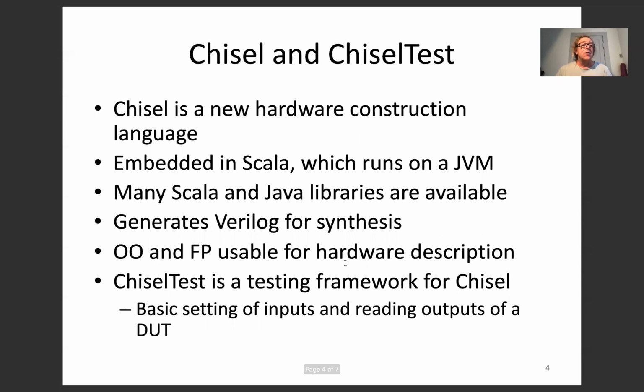So you have the whole world of Scala and Java libraries available for your hardware construction and also for your hardware testing environment. For example, if you're testing a processor and you want to read an ELF file, you might find a Java library to read an ELF file. Chisel generates Verilog for synthesis. So it uses Verilog as an intermediate language, and we can use all available tools.